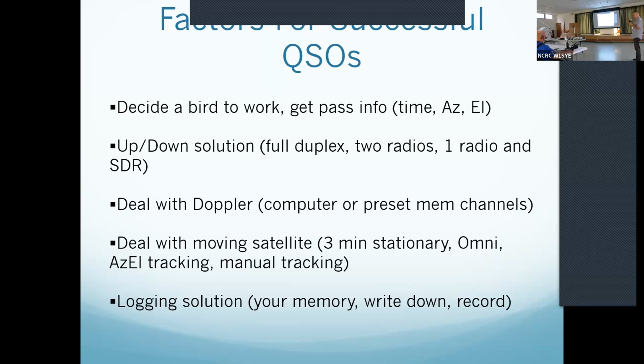So when the satellite's approaching, you put on 1, then you try to make a contact, and then you'd have to switch it to 2, and you can hear the receive start to get scratchy or come in and out more, then you just turn it 1 more memory channel, and then you start hearing them again, and you could operate it that way. But the TS2000, you could lock and trace. Well, yeah, you can do that with the 9700.